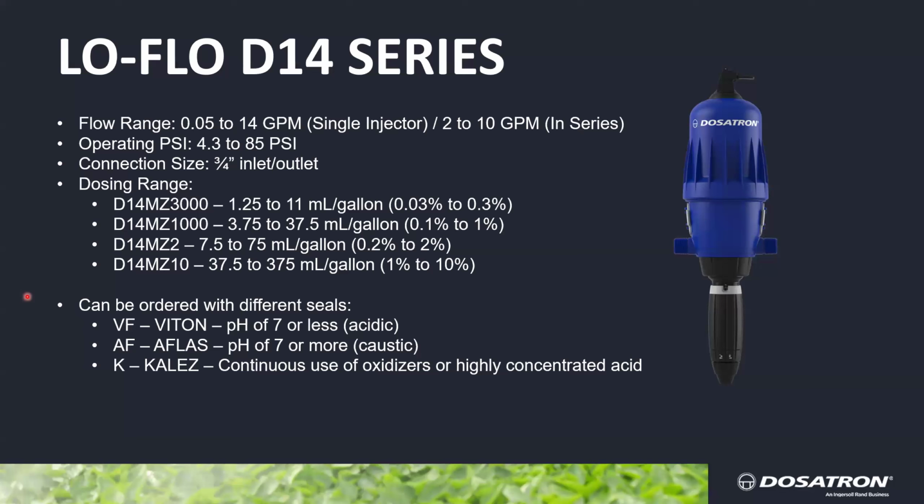Yeah, thank you. And if you're ever unsure of the product that you're using, there are some really good websites that have Viton compatibility. They have Aflas compatibility, or you can even look up CalRes compatibility. I would find that CalRes is almost compatible with everything that I've ever searched. Being that it is a very expensive seal, though, if your Viton is compatible, then go ahead and use that.